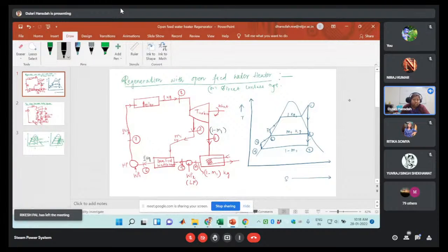That condensate will be pumped to the heater at point 4. That pumping process will be an isentropic pumping process. This one is pump 2. Last class we had not included this connection, so that's why you were getting confused. This one is your pump where we are giving the compression work or pump work as work input. It is the low pressure pump.